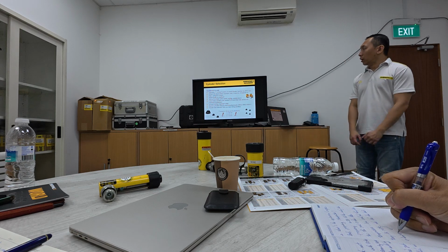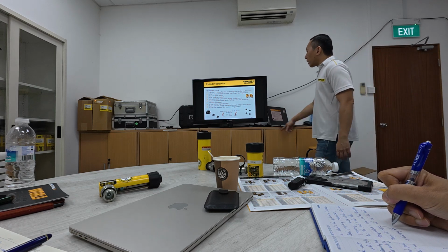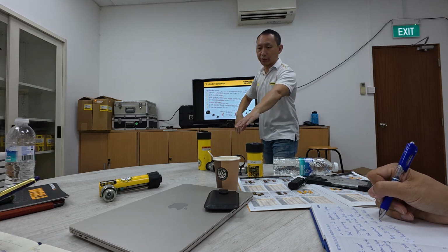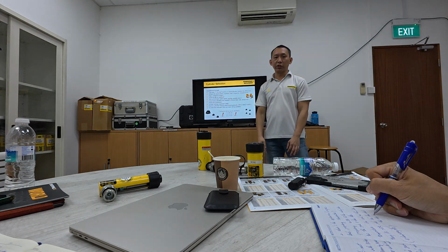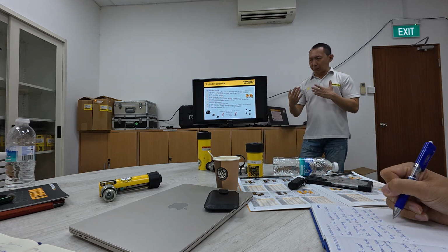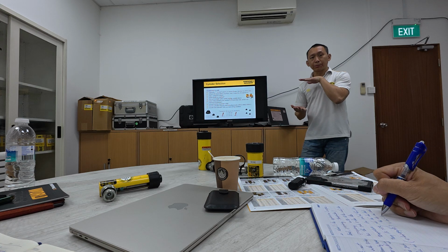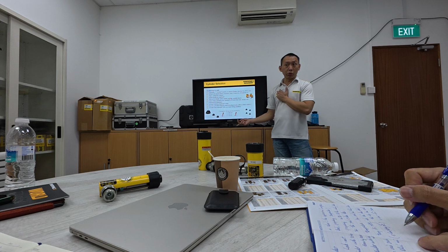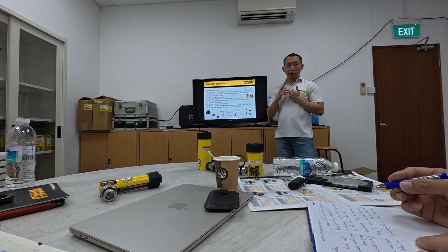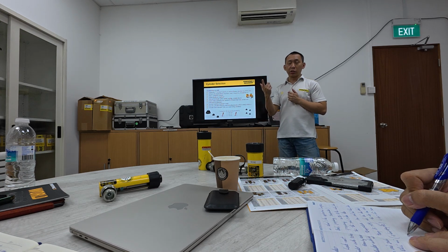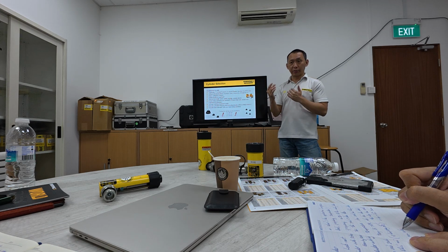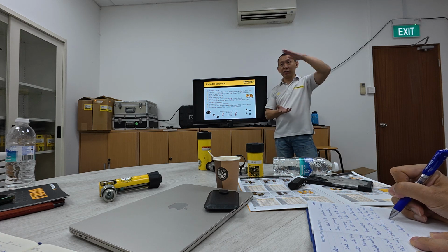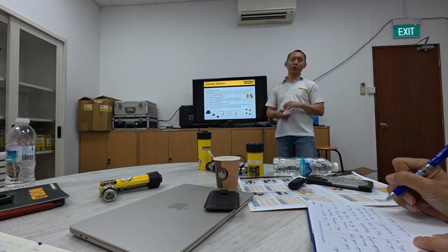Okay, so next thing, the length. Because what's the height of this? The height, yes, very important, especially for applications with space constraint. So you have to recheck the length. Then of course the stroke required, how much stroke is needed. And then of course bear in mind the 80% rule, because if the customer can accept the 80% rule, then obviously you can try to sell one bigger cylinder. Of course, bigger cylinder, higher value.